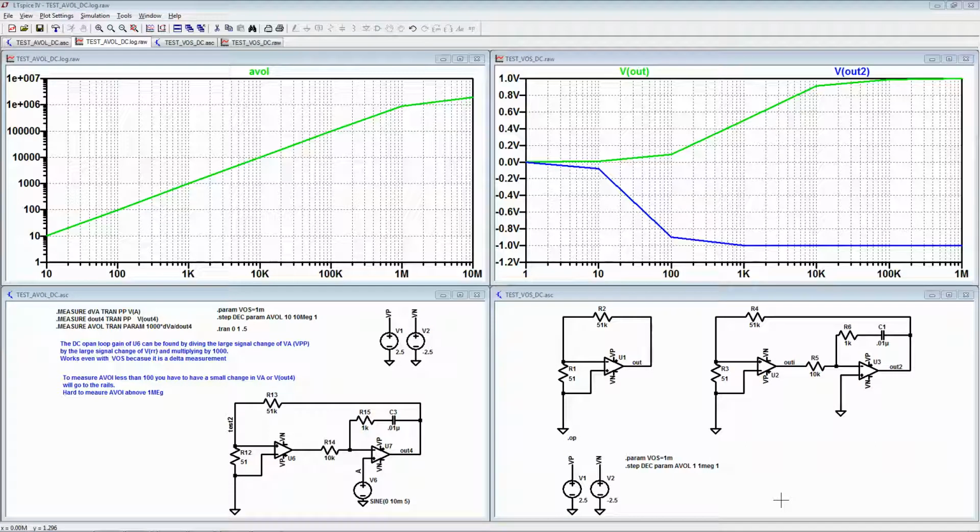So today we're going to talk about some important test circuits, going through what seems to really be important when dealing with integrators, which is the heart, besides the multiplier, of the quadratic integrate and fire: the open loop gain and the offset voltage. Now, gain bandwidth would also be important, but with a time constant of 1 for our integrators that I've been using, we can get away with smaller gain bandwidths, and so we've been trying to maximize the open loop gain at DC.